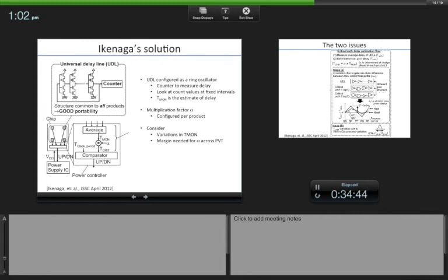That is the tuning portion. You tune your delay lines to that particular product by figuring out what alpha is, and that product gives me the estimate of the actual critical path delay, which you then put into your feedback loop to adjust and get to where you want. So that goes to your power control.